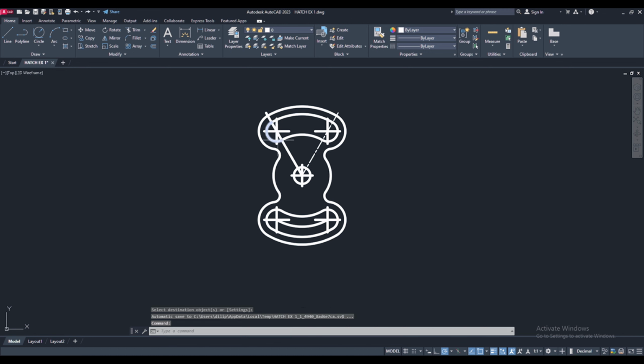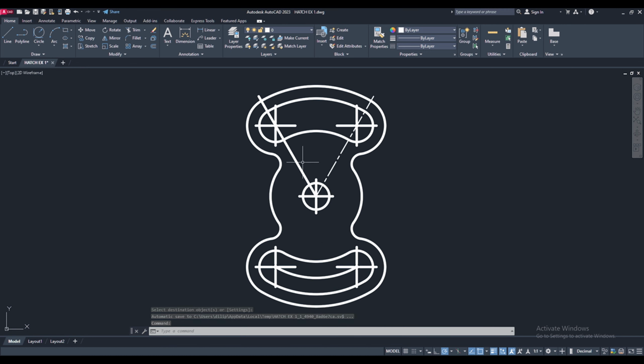After that, here I can see there are some center line parameters. Those need to be of different line property, so no need to worry. Go to match prop once again by clicking on this icon. Select the center line property and paste it with those center lines like this. Okay, so we have successfully maintained the line property of the entities.